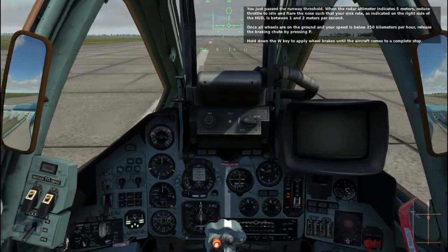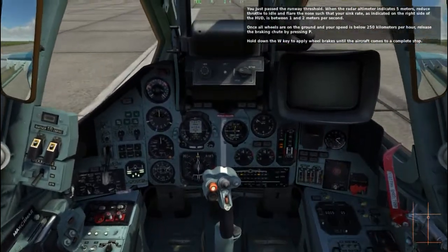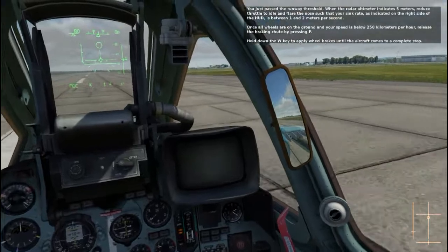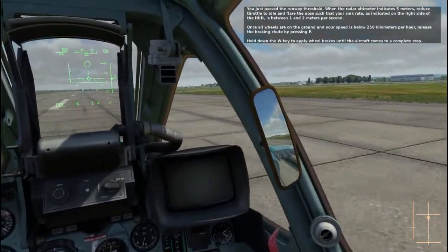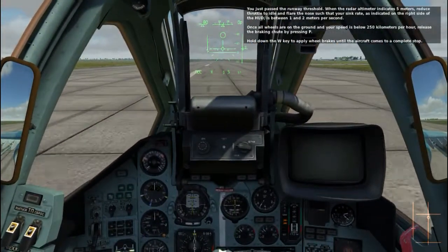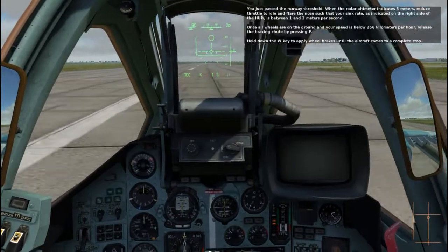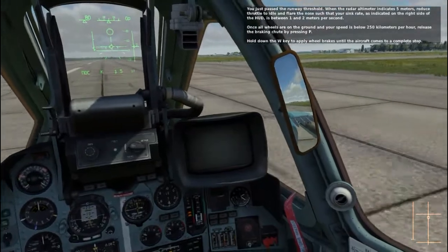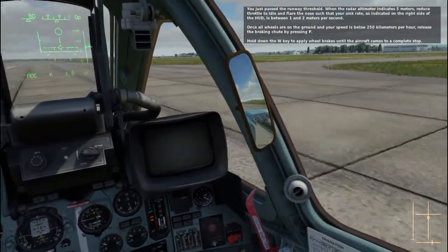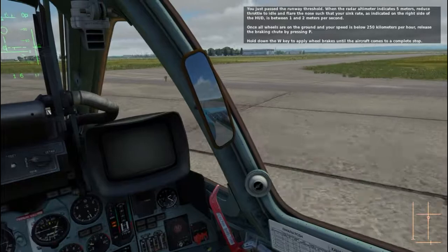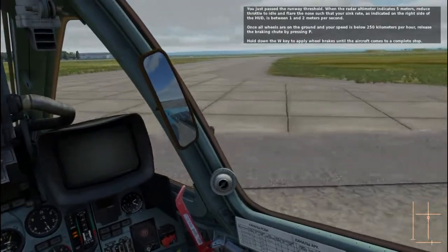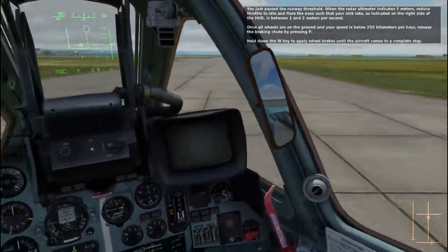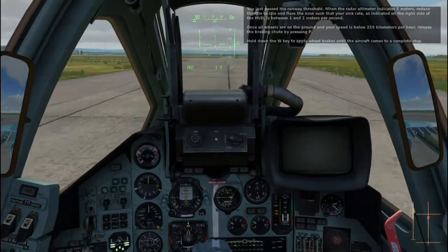Well, that wasn't my best landing. I should have just crossed the threshold like I normally do and then cut the throttle to land. We were light enough that his direction was technically correct. I just like that bit of extra speed on the way in case something goes wrong. And changing my mind at the last second wasn't the best decision. I had to hold off that landing and touch down harder than I would have preferred. But any landing you can walk away from, I guess.